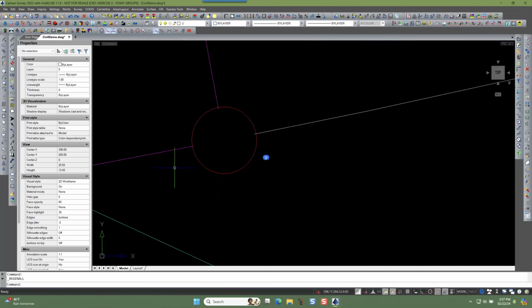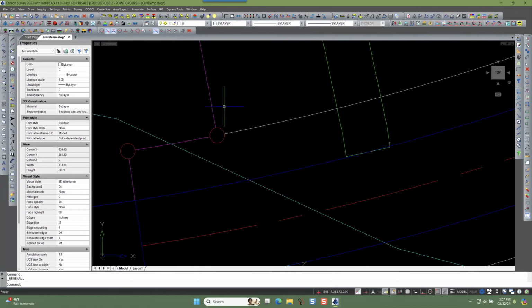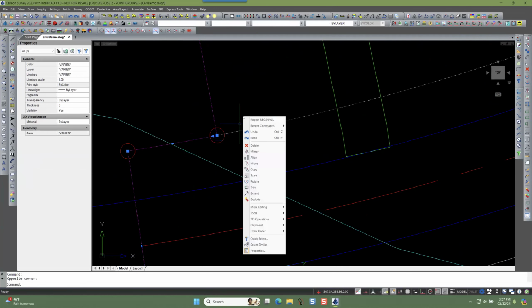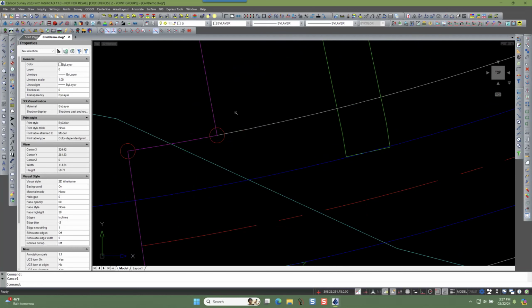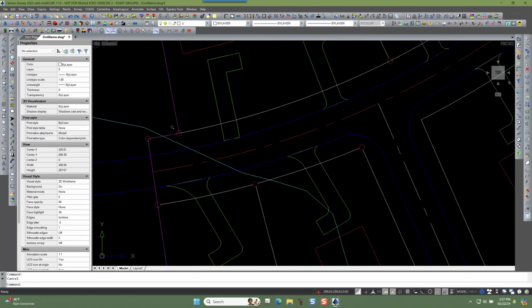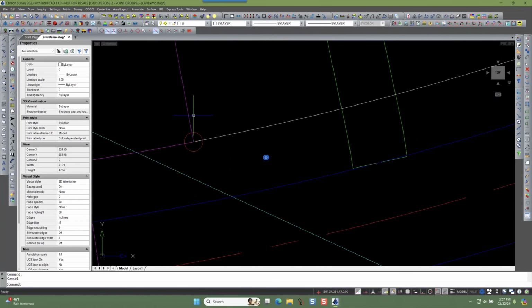My wipeout is hiding the lines that go underneath the corners. Now, maybe you've modified some of this and it changes the draw order. You get some that look like this. You say, oh, I thought they were supposed to be hidden under there. Well, it's simply because the lines were modified that they got brought forward.